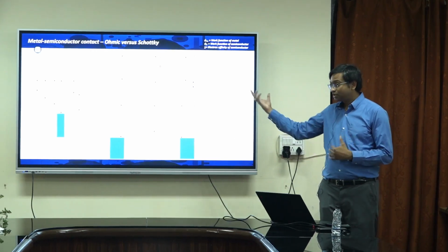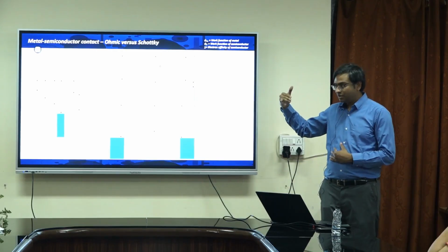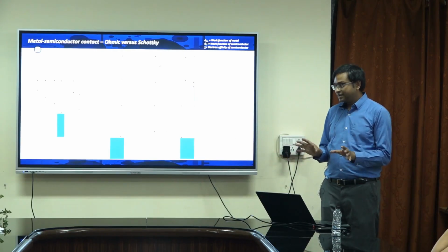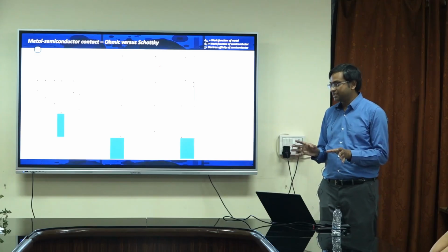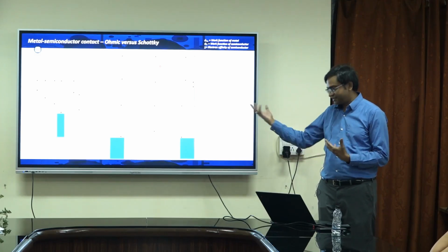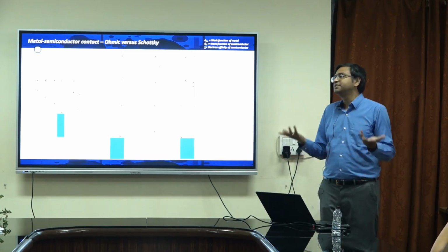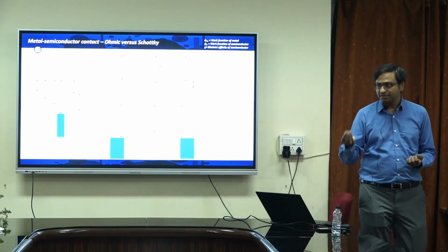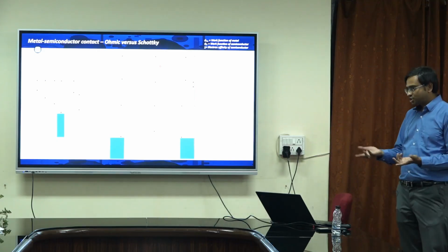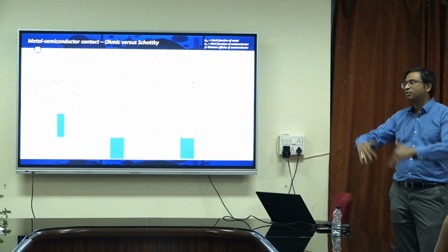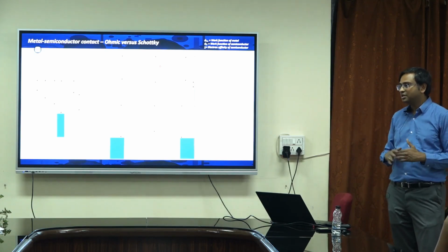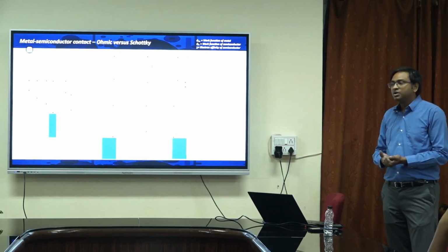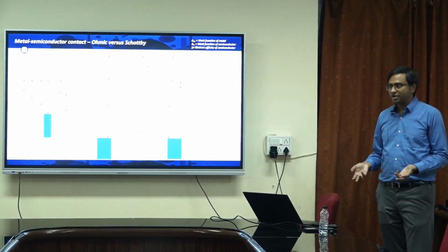We have to, because you saw that in order for me to get to the IRDS roadmap, I need an ohmic contact in the first place, because if I don't start with the ohmic contact, with the Schottky barrier, my contact resistance starts with a larger number, right? At the end of the day, what is my objective? It is to reduce the contact resistance. And Schottky barrier is like, as I told you, if you have a wall in front of you, if you are going somewhere, you have to cross that wall, you will be slowing down, correct? So there is no other option but to make an ohmic contact.